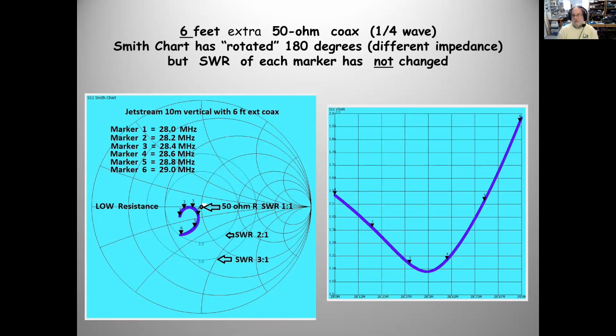That is so cool. I could not have explained that to you a year ago. So this NanoVNA has forced me to rethink transmission lines, coax. Now, this would not have happened if the SWR is 1 to 1. Why? Because then all the points would be right in the bullseye, and no real antenna does that.